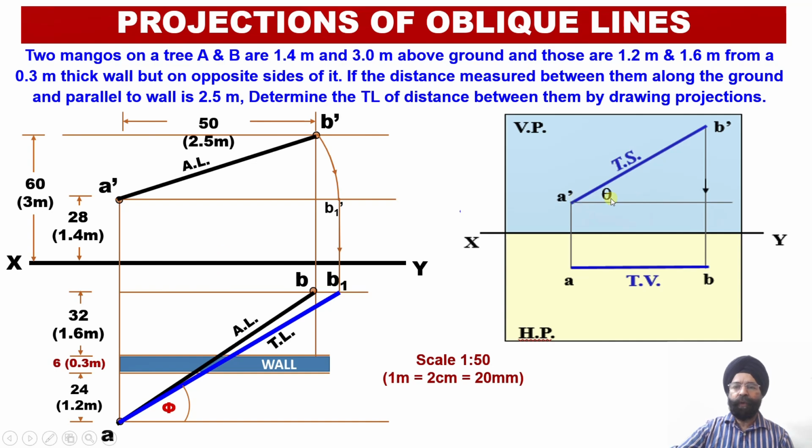In order to evaluate the true length of the line in the elevation, we must ensure that the apparent length projection in the plan is obtained parallel to the vertical plane. The moment we obtain the apparent length projection parallel to the vertical plane, the projections drawn through these 2 points onto the vertical plane will provide us with the true length of the line in the elevation.